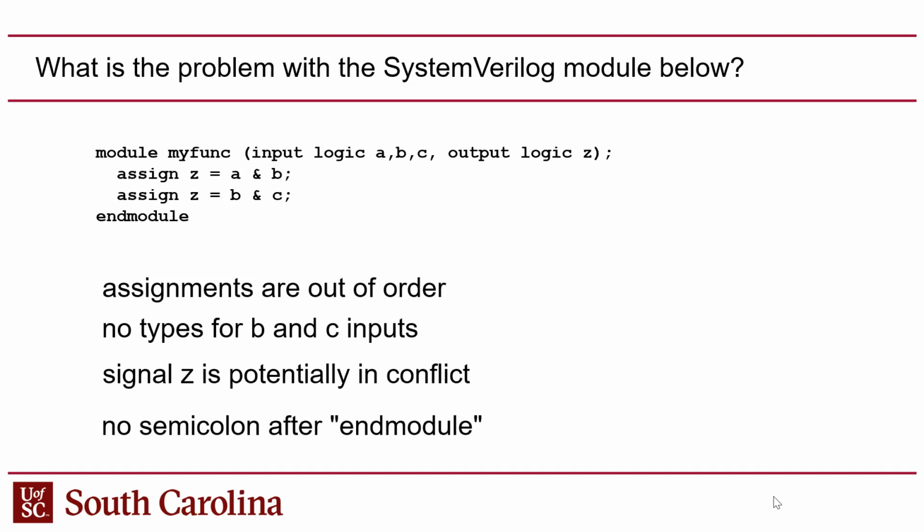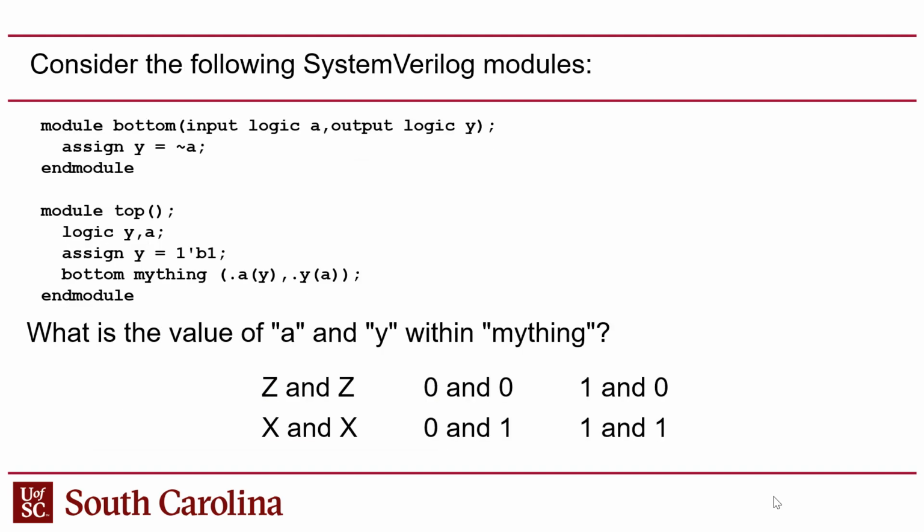So we talked about how you set up a module. This is just basically syntax. Make sure you've got the semicolon at the end of the module statement. And we talked about assign statements. Structural versus behavioral. Structural is schematics, right? Interconnections, instantiating modules. Behavioral is assign and always statements. We talked about how Verilog has 4 states, which is not enough for me because I like VHDL. VHDL has, I think, 6 states for each bit.